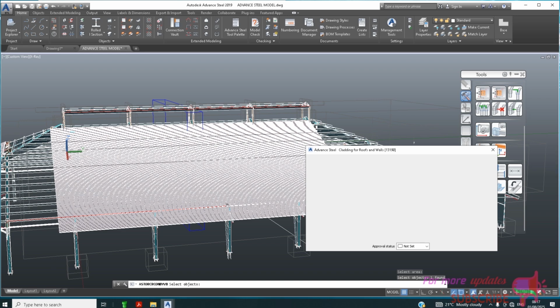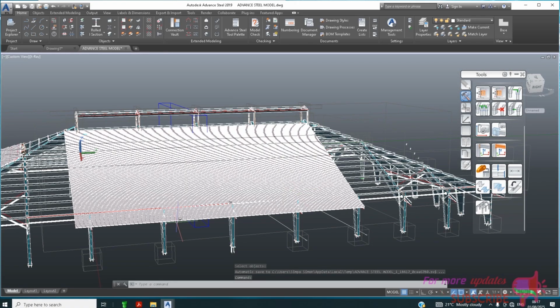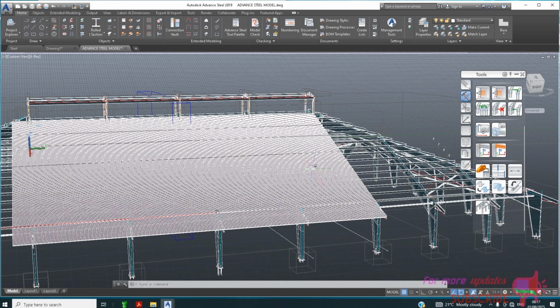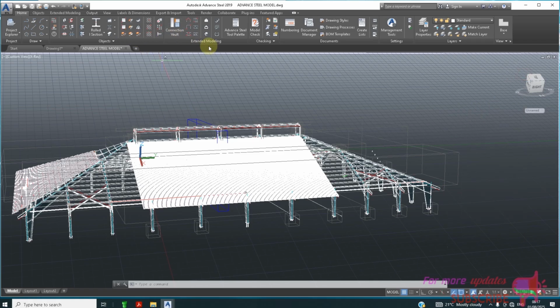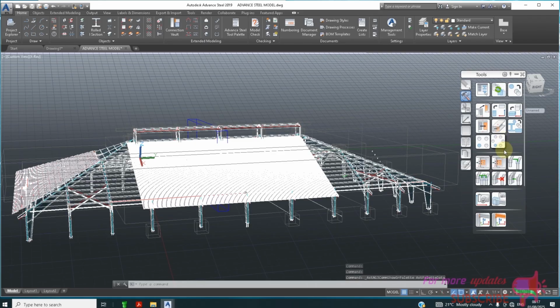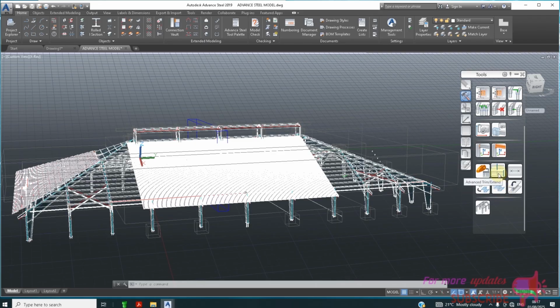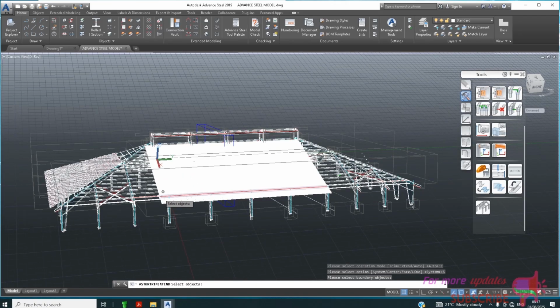I'm not going to set properties. I'm just going to go ahead to the next step of extending. You can see the angle is off a bit, but we have that angle. We can just now go to tools, advanced tool palettes, scroll down to extend or trim, advanced trim or extend, and then I want to extend using systems. So I will start with one side.